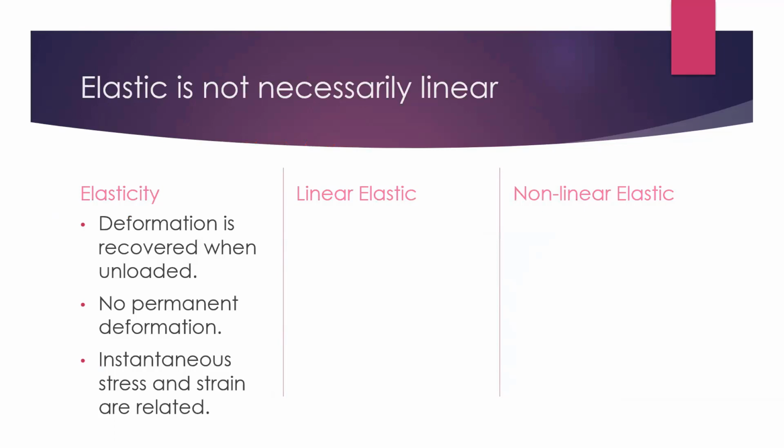And it's very easy to mistake elasticity with linearity. And in fact, if you notice, I have even just done that. Linearity is something entirely different than elasticity, but in most practical purposes, we see them going together. So linearity means that your stress and your strain are linearly related.